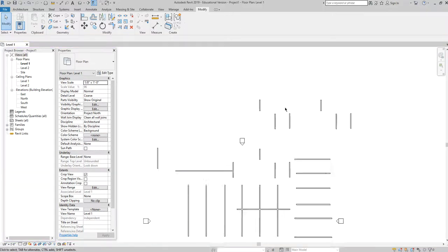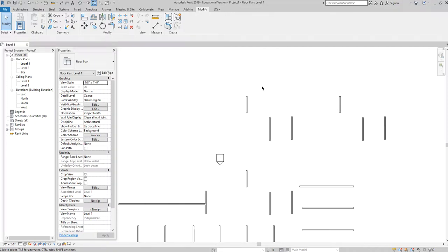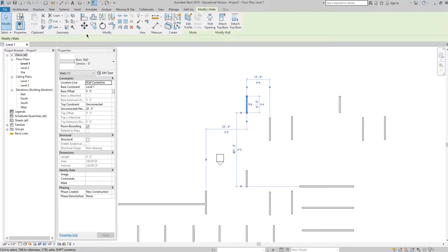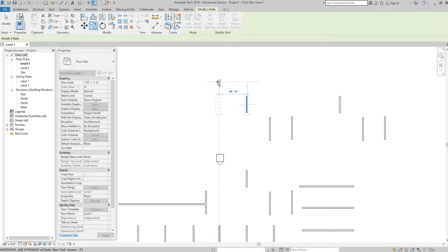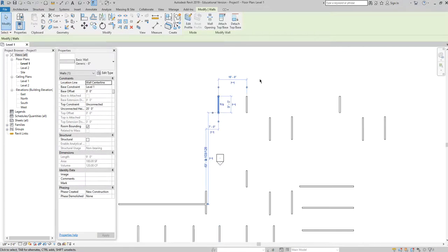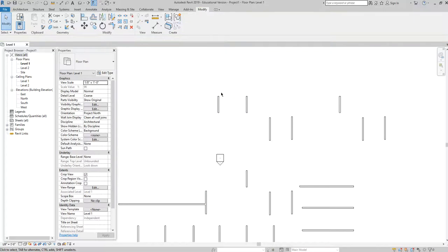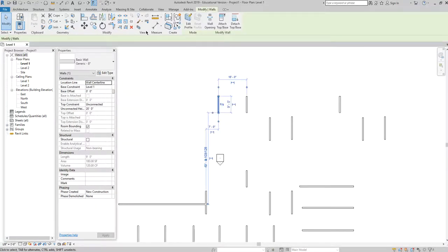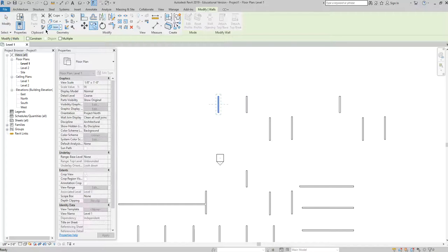Now, what you're essentially seeing here is that the copy command by default is only one singular copy. So I can grab something, I can copy, click, but the command finishes after that, right? There is the option, if I select something, I click on copy, again, a little tiny checkbox right here, multiple. If I want to create multiple copies and have the command continue instead of end after one copy, I check that little box, click, 1, 2, 3, 4, I'm just clicking, click, click, click, click, click, escape.